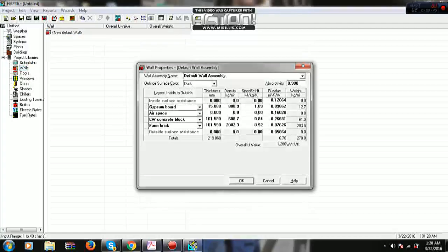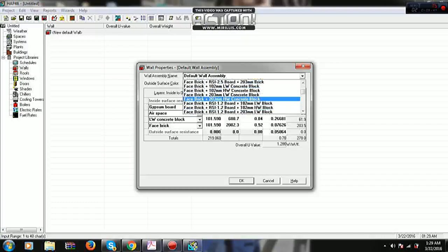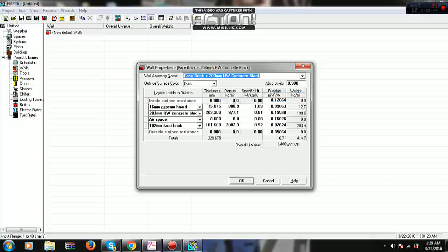Right. So again I will do the same thing from the start. Walls. Now, so I know the U value. Just note down for the wall it is 0.437. This is my target to set the U value for the wall. So how can I do that? I will randomly select any kind of construction material in order to reach that 0.437. If I select, for example, this one, 0.347, very near.